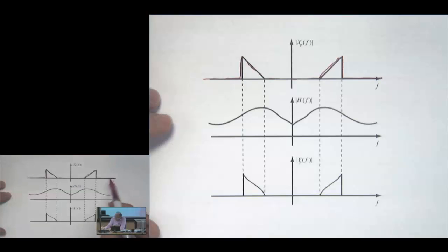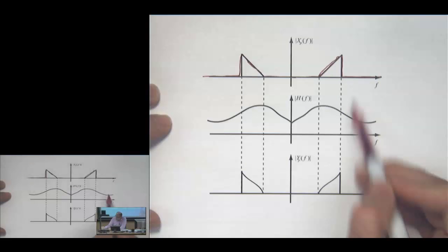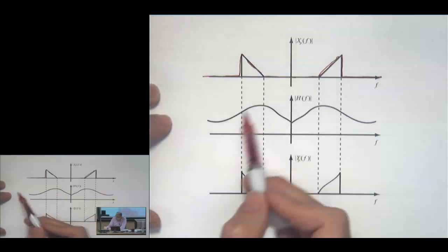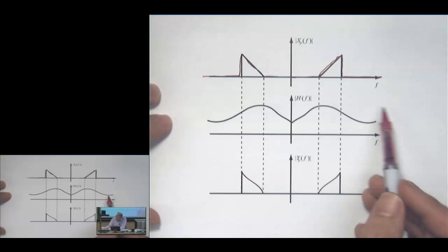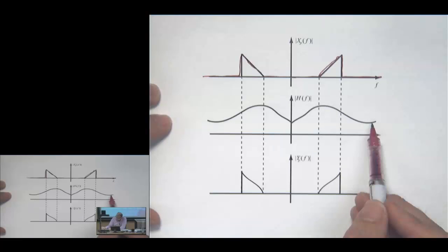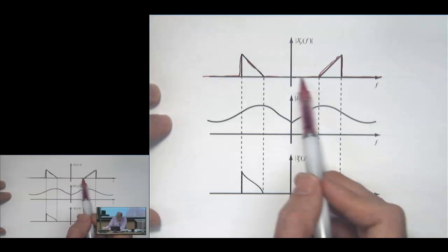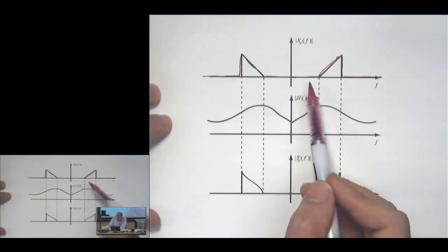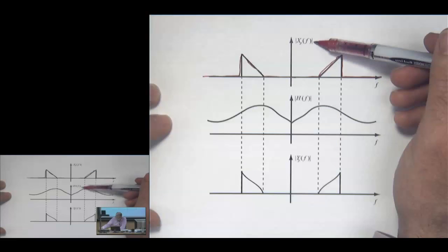Okay, so the basic idea is as follows. We are going to send this signal through this channel, and look at this channel impulse response. I've just come up with this arbitrarily. It could be, of course, much more complicated than this. Now, what you note here is that this part of the signal is 0. This is convolution, so in the frequency domain, we're going to multiply this signal by this signal to get this one.